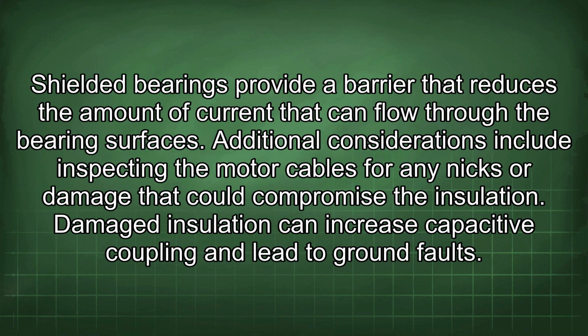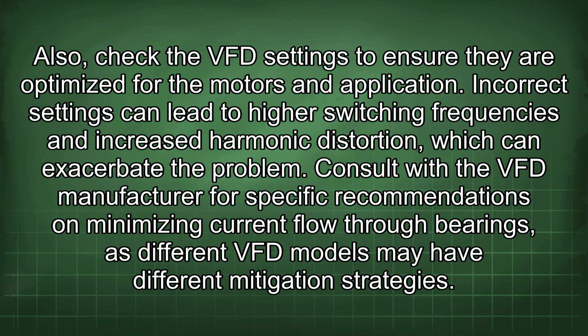Additional considerations include inspecting the motor cables for any nicks or damage that could compromise the insulation. Damaged insulation can increase capacitive coupling and lead to ground faults. Also, check the VFD settings to ensure they are optimized for the motors and application. Incorrect settings can lead to higher switching frequencies and increased harmonic distortion, which can exacerbate the problem.